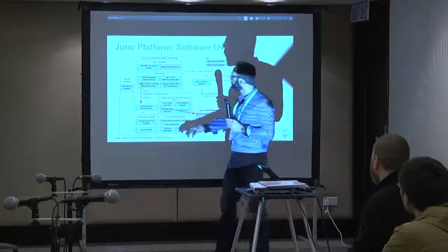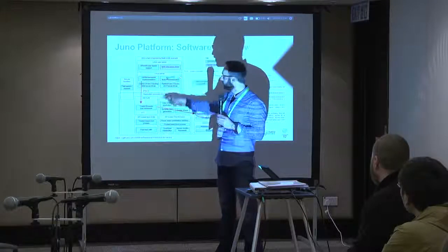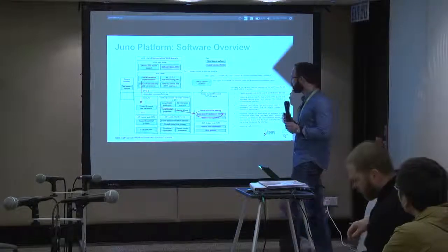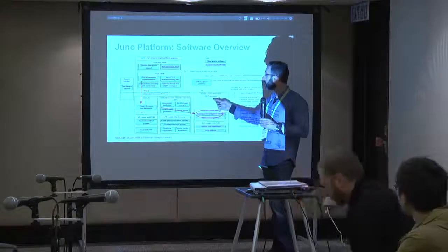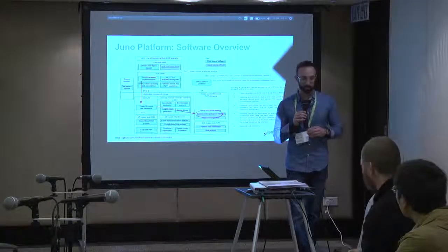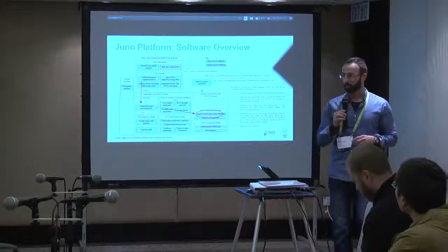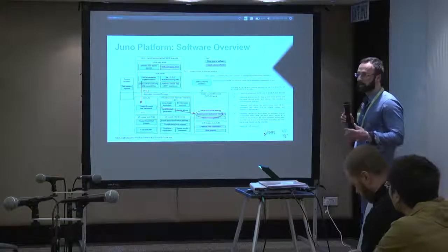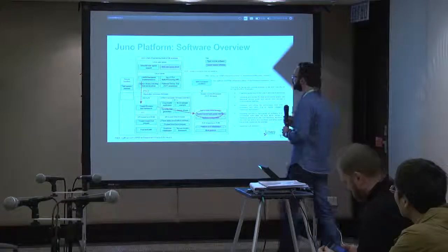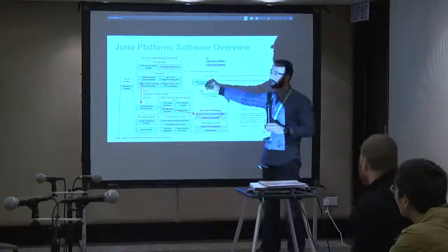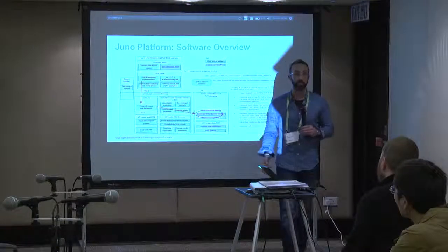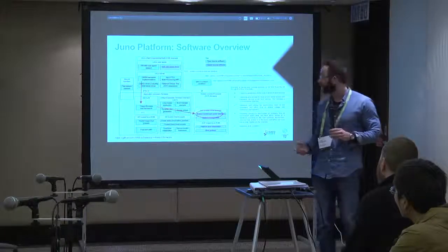As I was saying from the beginning, the PSCI defines the interface between the rich OS and the ATF. Well, in Juno this is called the SCP. That's the one that controls the power modes. Some of the other operations are not detailed in PSCI, and there is an SCP interface using the MHU to control the dynamic aspects of the platform. I suppose all the devices are not covered by PSCI.